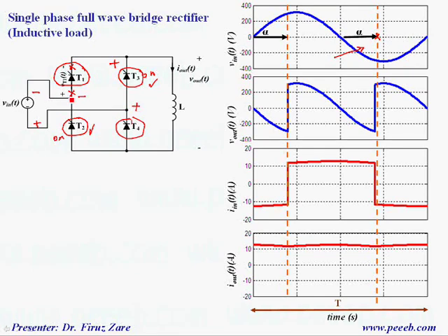That means this polarity is negative because this thyristor is on. And based on this positive voltage, you can see that this thyristor should be off because the cathode is positive with respect to the anode. That means the voltage across thyristor 4 is negative, and the voltage across thyristor 1 is negative. So in this case, this thyristor should be turned off.